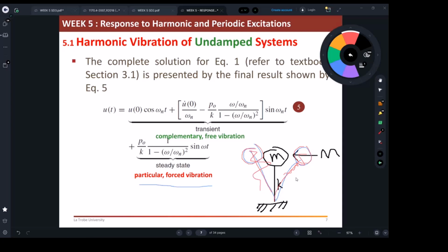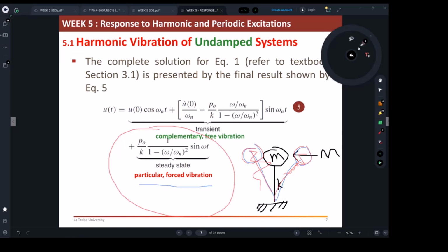Now, the main one is the one which is developed from the forcing harmonic motion. The second one, which is kind of shaking as it's moving left and right, is a free vibration, which we know in reality should go away because there is damping. I know at this stage we're talking about undamped systems, that's what we said in this section, but this is just for you to understand the theory and the concept. But in real life, we always have something to damp a vibration, whether the air, even the air itself can resist motion.